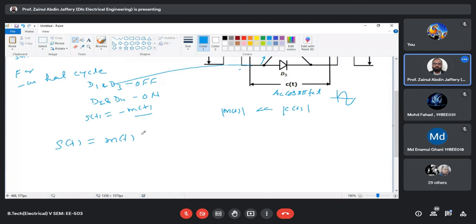you can give a gating pulse, a pulse, that is, you can write this as -1. Okay. Writing -1 is a little difficult, so let us do it like this. So actually you can say this becomes a product type signal p(t), pulse train, and this will be a signal like this, right? So you are multiplying a signal like this. This will be +1 and this will be -1. Okay, so this becomes, let us say, signal p(t).